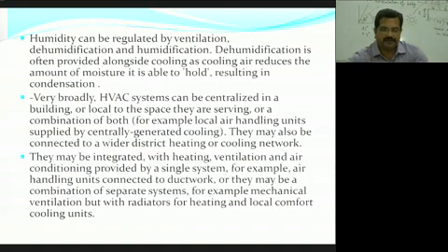Humidity can be regulated by ventilation, dehumidification and humidification. Dehumidification is often provided alongside cooling, as cooling air reduces the amount of moisture it is able to hold, resulting in condensation.